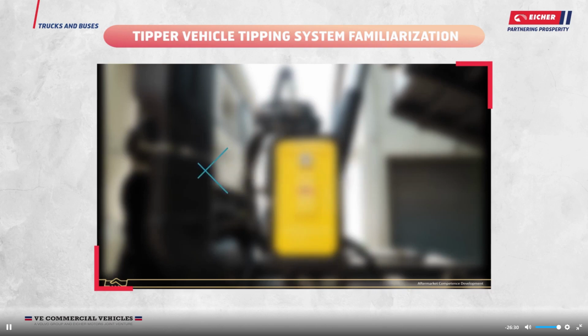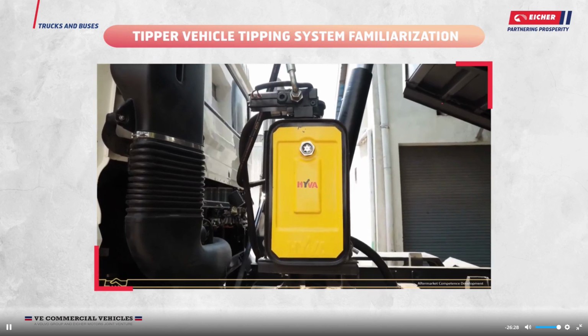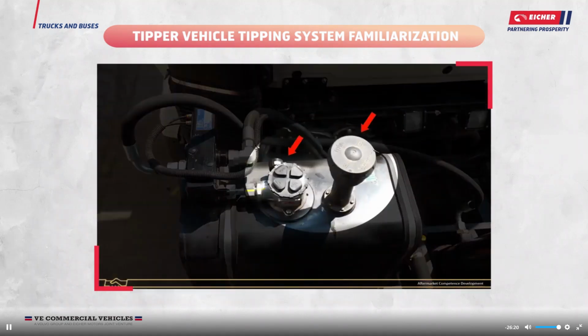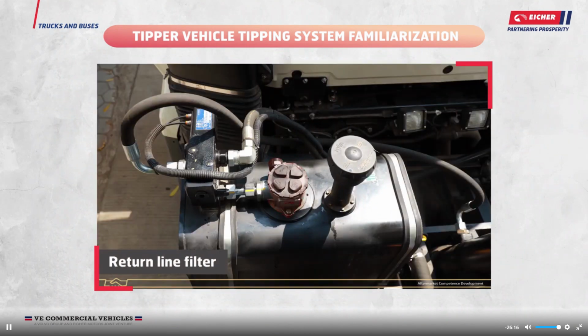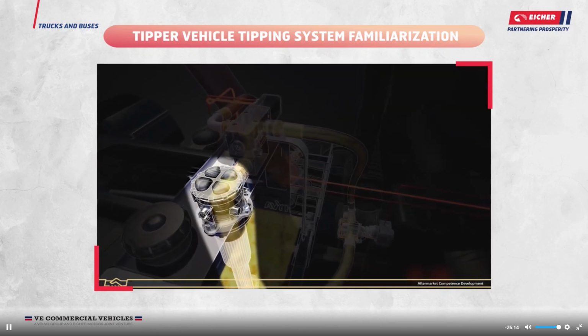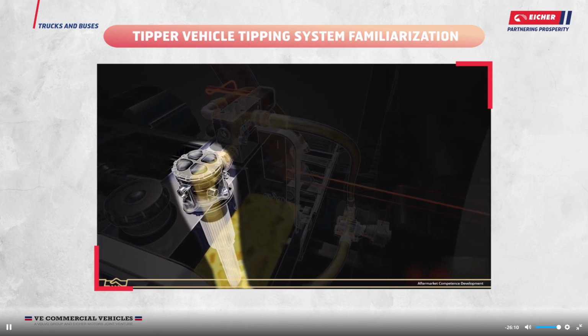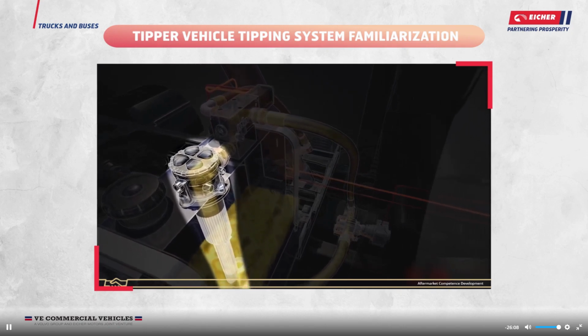Hydraulic tank. It stores the oil as per required quantity. Oil quantity can be checked through oil level indicator glass provided on the tank. There are 2 filters provided on the tank. One is the return line filter. This filter purifies oils in the tank by cleaning the contaminated and worn out metallic parts in return oil.